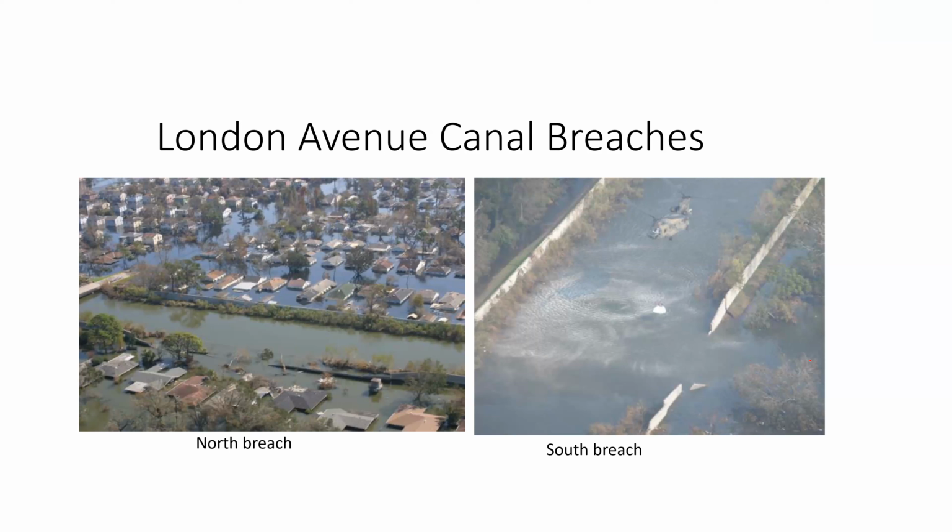Okay, first of all is the pressure, how much pressure is coming out. There are so many things connected with it, but I just wanted to let you know for today's class that a piping failure means there is going to be internal erosion. There will be so much internal erosion when the water is coming out with high pressure. That is going to create the piping failure. If the soil is good enough to cut down the pressure buildup due to the seepage, then it's okay. But if the soil doesn't have enough permeability, the hydraulic conductivity is a resistance. Always remember that. It's resistance to how much water pressure is coming in.